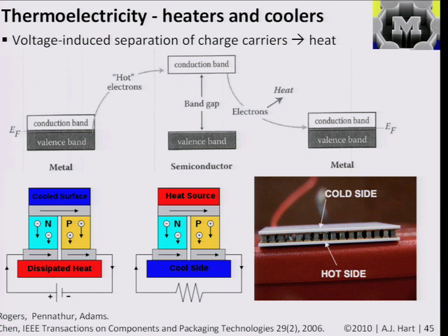And one will be, they call it N-type, which will have an excess of electrons, and the other will be called P-type. So there'll be a lack of electrons, and the carriers are called holes, which are basically, you can think of them like positive electrons. And the idea is that these have opposite thermoelectric effects. So as the current goes from here to here, in this case, this end gets cold, and in this case, this end also gets cold, even though the current is running in opposite directions. So each of these little couples, this pair, can be used to generate heat or to get electricity.